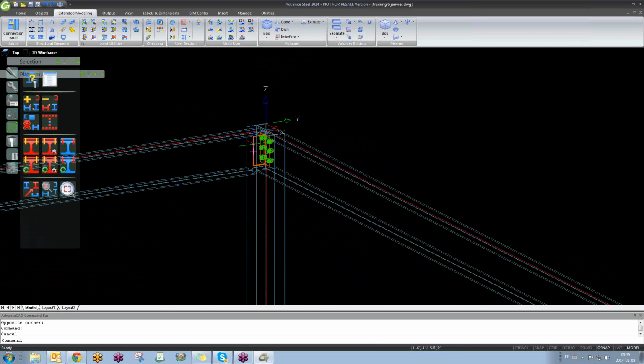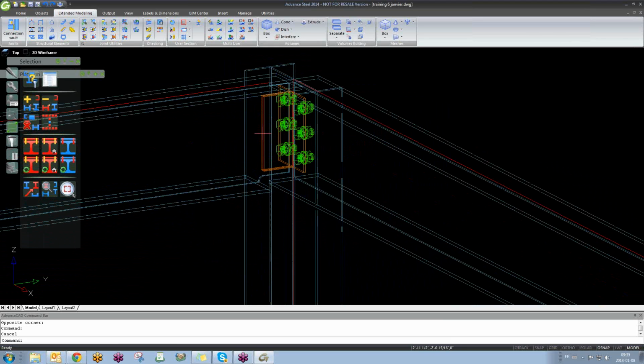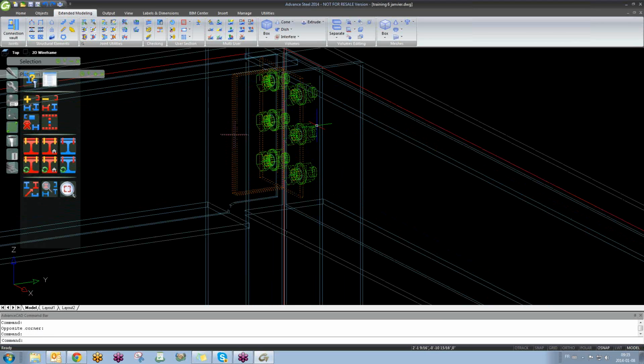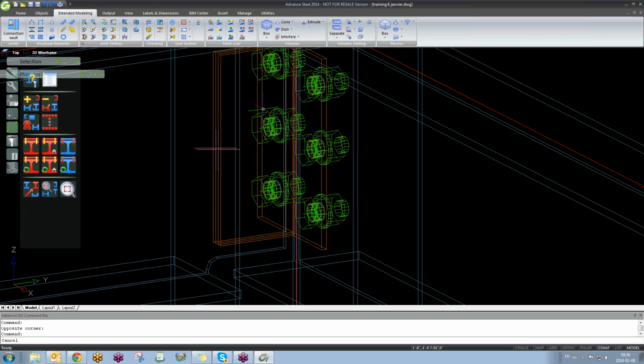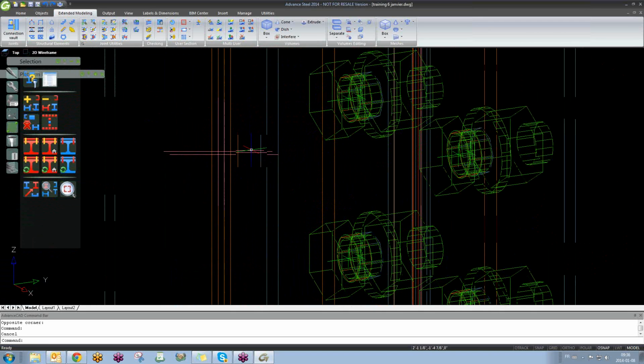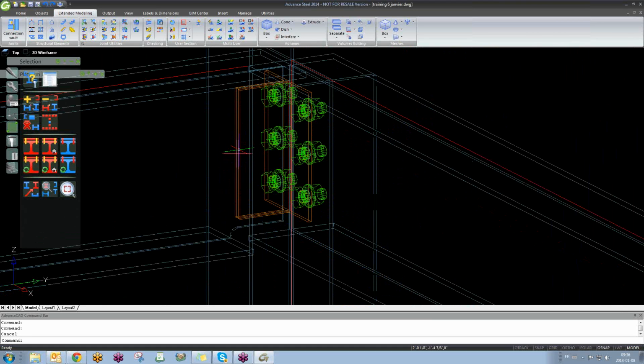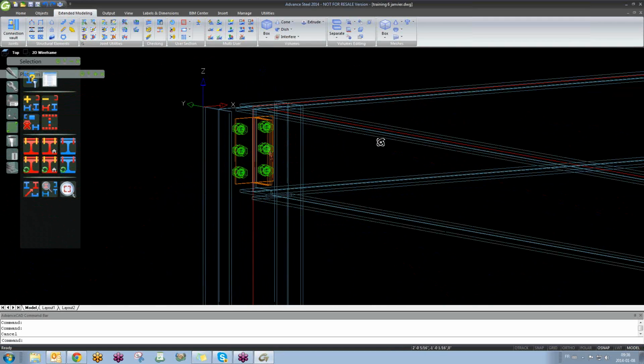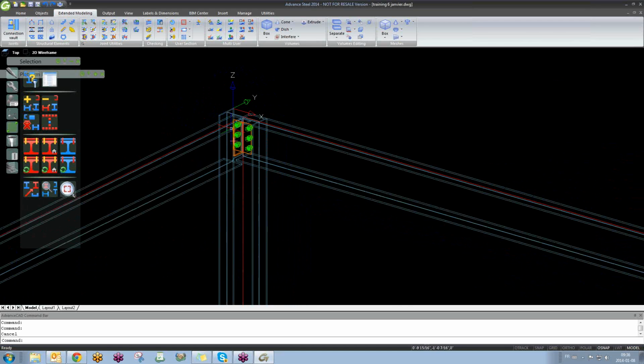This is an assembly, but it's not done like this, where the welds are on site and the bolts are done on the site. That's what I'm trying to explain. So this would be correct if the clips were shop and the bolts were site. The way that you have explained to me, this will work. Just don't put all of them inside or all of them in shop. Inside it's correct, but in the shop this will create a problem. You cannot say shop bolts into any beam.